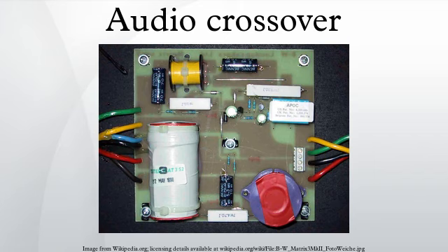Typically, the possibility of an easy way to vary or fine-tune each frequency band to the specific drivers used. Examples would be crossover slope, filter type, relative levels. Better isolation of each driver from signals handled by other drivers, thus reducing intermodulation distortion and overdriving.